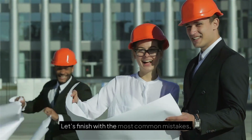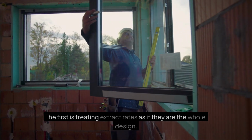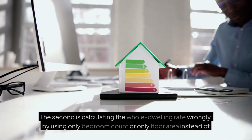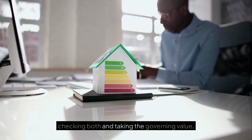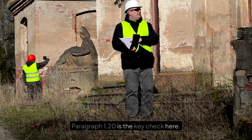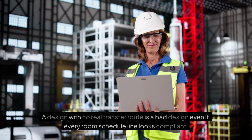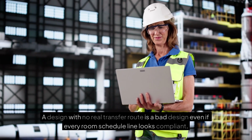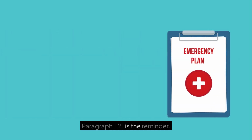Let's finish with the most common mistakes. The first is treating extract rates as if they are the whole design. They are not. The second is calculating the whole dwelling rate wrongly by using only bedroom count or only floor area instead of checking both and taking the governing value. Paragraph 1.20 is the key check here. The third is forgetting the air transfer path through the dwelling. A design with no real transfer route is a bad design even if every room schedule line looks compliant. Paragraph 1.21 is the reminder.